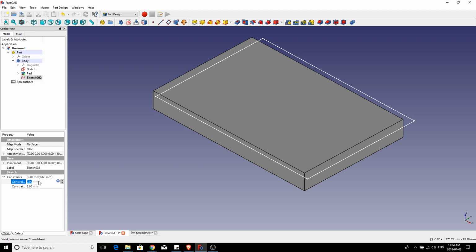So I'm going to highlight the first one that's got the formula. I'm going to click the formula button, copy the formula, just like this. I've got to say OK, because I don't want to discard that. Now I'm going to go to the second value, click its formula button, paste that in there. Now here's kind of a funny little thing with the UI here. If I just hit enter, it's not going to keep my formula, and I can't actually click on the OK button down here. So what you have to do is actually click the card offset to accept its hint there. It gets you out of that drop down, and now you can hit OK.